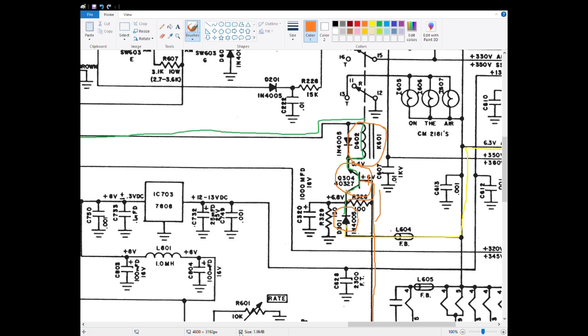So I was coming back here to look at why did I have an AC voltage at D301, but absolutely nothing on the output. So I tested it. Actually, I pulled it out of the circuit, and I tested it with both an ohm meter and a diode checker, and it wasn't open, and it wasn't shorted. It was just an erratic reading, and we'll go down and I'll show you that, and you'll see what that looks like. And then we'll see why.